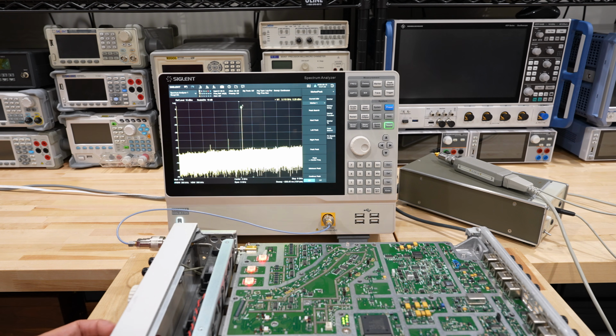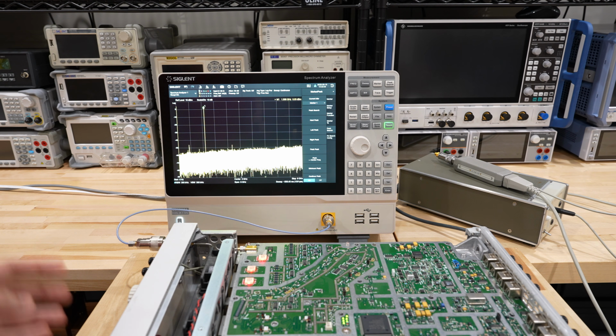And let me check the screen. Yep, no fractional error anymore. That is fantastic. Of course, there's a lot of junk because it's not closed yet. Look at that. That is great. So perhaps the gain of the detector had deteriorated to a point where the loop was unstable. This was a pretty subtle problem, I have to say. So I'm quite excited. Now, this doesn't completely mean it's fully fixed because we need to do some performance verification to make sure the phase noise and everything else is okay. But that is super promising.